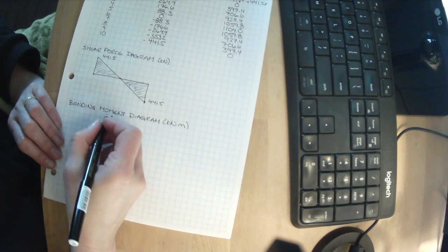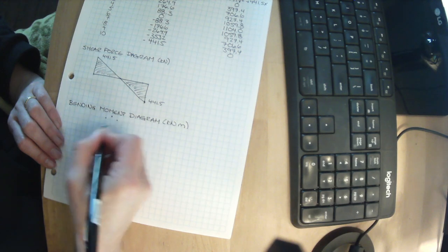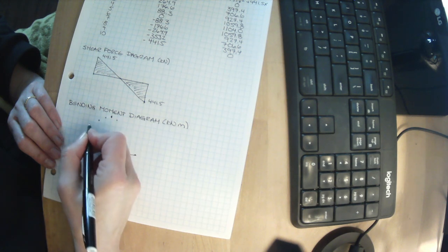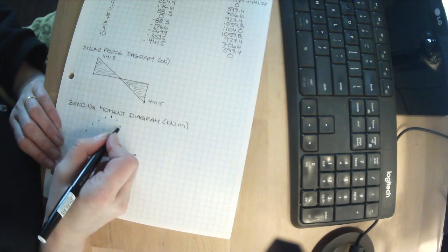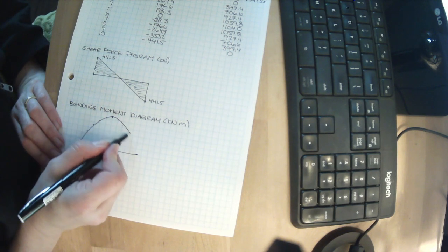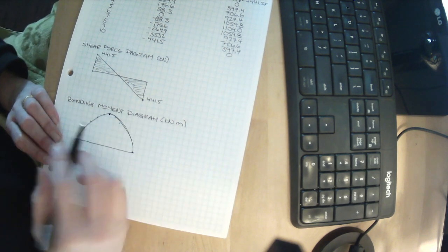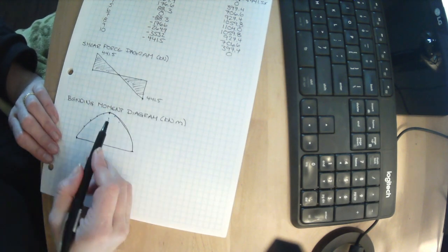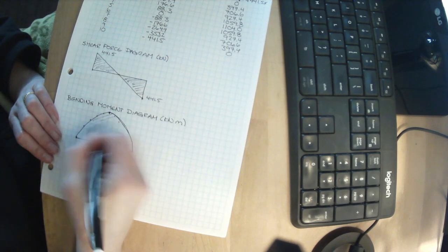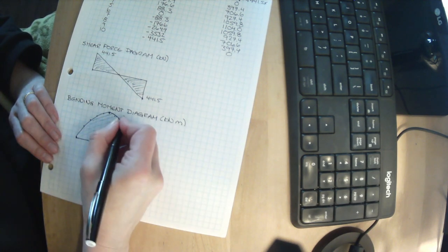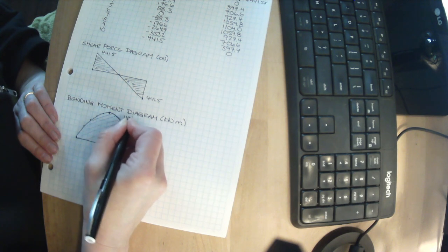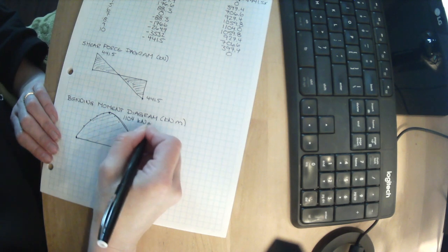What's interesting though is that it is not a circle. I guess that's even lower. It is a quadratic equation. So this is not half of a circle, it is a quadratic equation. So it drops off more rapidly as you get closer to the supports. The worst case moment is at the middle. And it is a value of, we calculated that as 104 kilonewton meters.